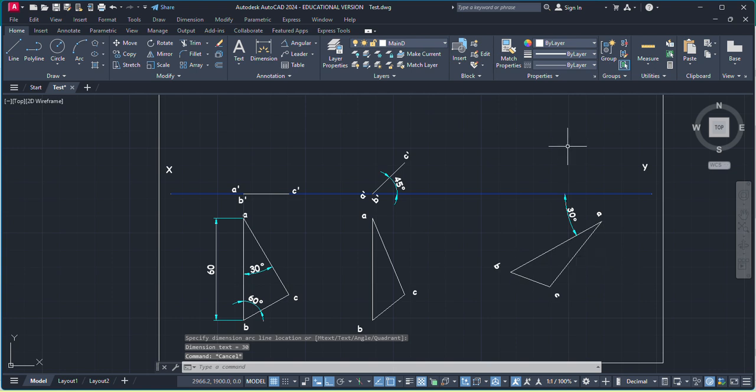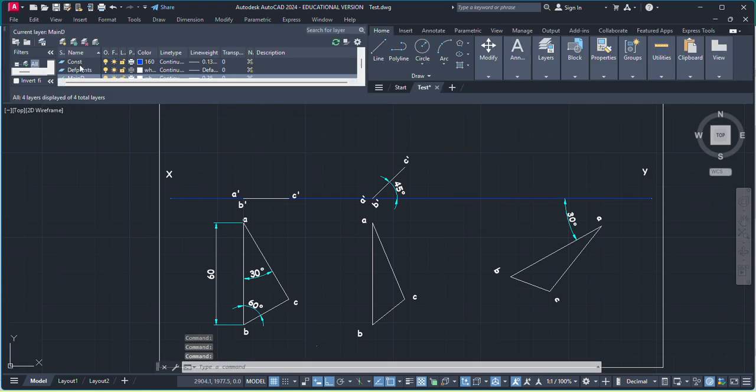Now from the top view you have to trace out this one front view. As we know, this is the longest side and this side is kept on HP. So while keeping this on HP, and it makes an angle 30 degree with the VP. So in the front view, this line will come in this reference line because this thing is on HP. So the projection of this line we get on the reference line. So do this thing, go back to the construction layer.